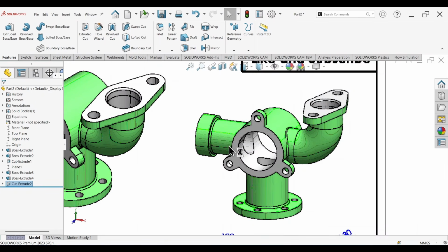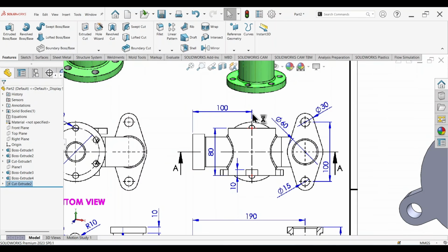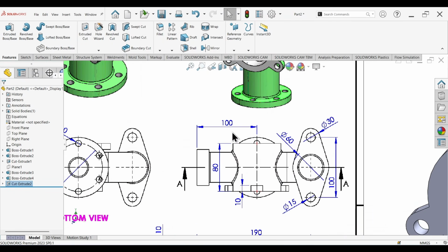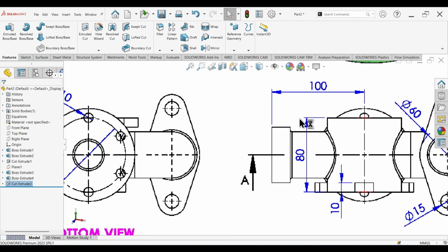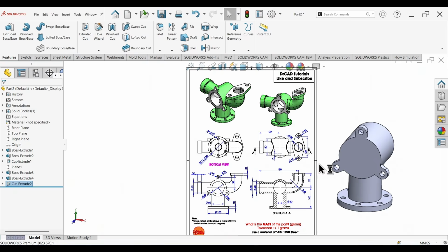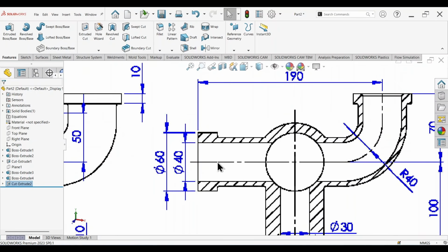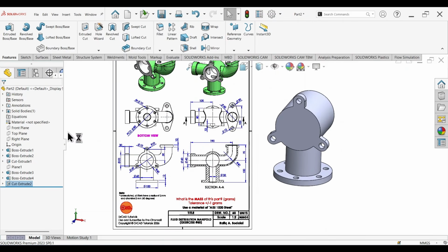So what we're going to do, and I want you to pay attention here. First of all, we need to create a new drawing plane in reference to the right plane of our component, at a distance of exactly 100 minus 20 millimeters. So that's 80 millimeters. So we're going to be exactly along this edge right here. And then we're going to draw a 2D profile, basically the path for the Swept Boss Base tool that we're going to be using, the circular Swept Boss Base tool, all the way to the top here. So let's go ahead and create the 2D sketch.